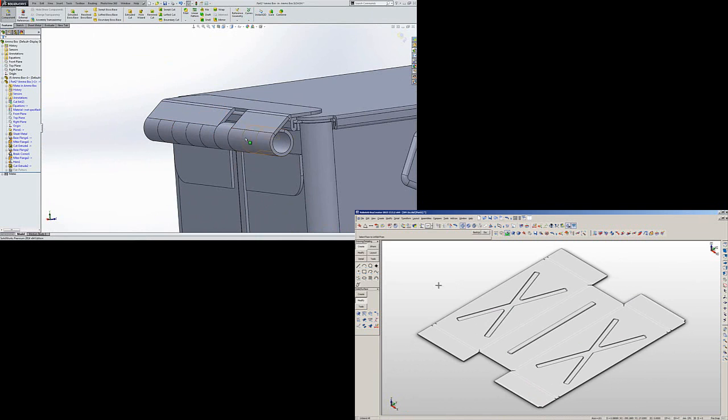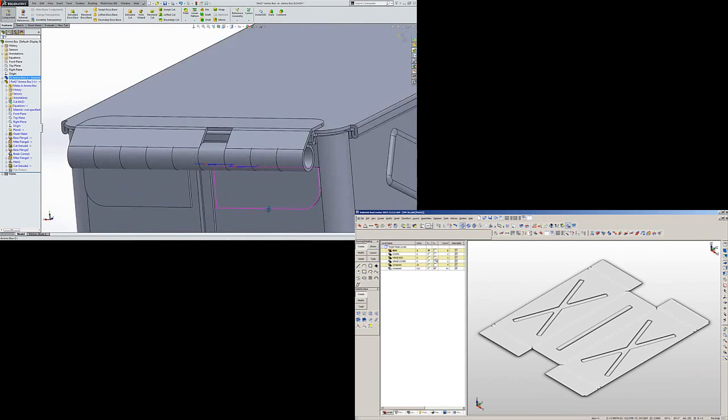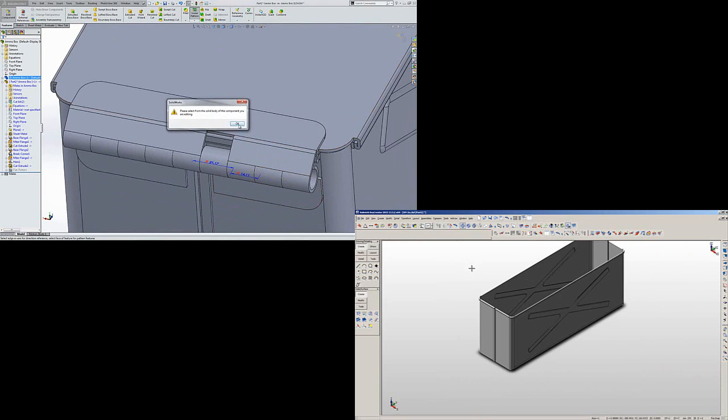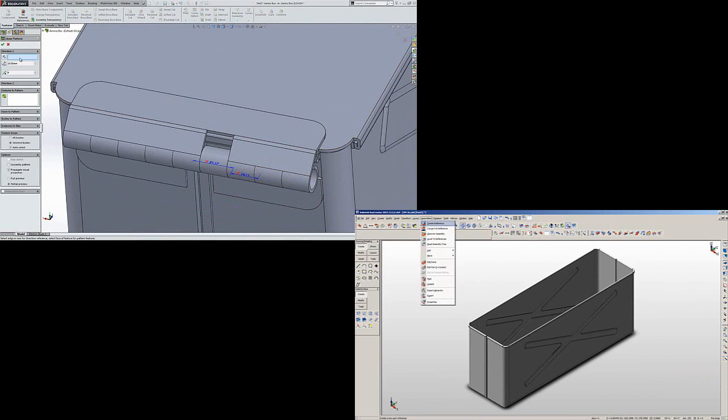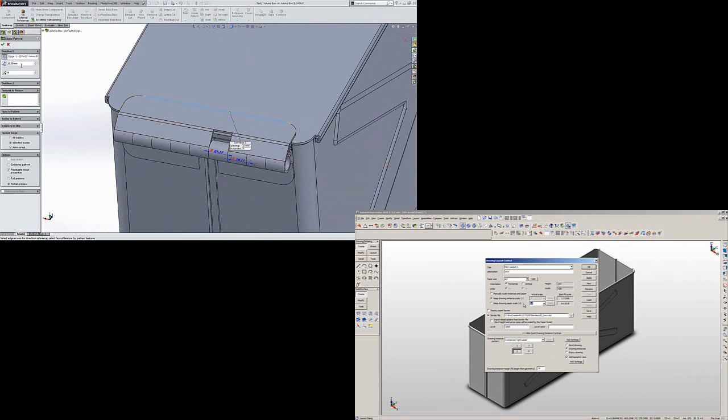So what we need to do is, again, double click our previous dimensions just to bring them up. We can go into our linear pattern now. That's fine, we'll just OK that. Need to remove that warning. Now we want to select an edge to be across. We just want to reverse that direction. So it's looking pretty good so far.